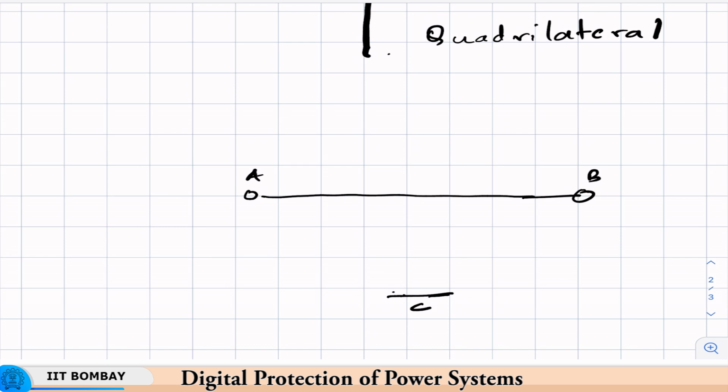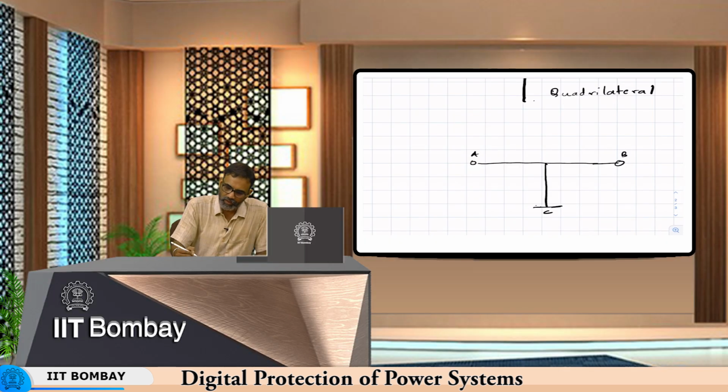So instead of, this is what the diagram shows, this is a tapping. However, realize that if the line is tapped, if there is a fault on any one section, then all, say all A, B, C, all the nodes will lose power. Instead of that, what is done is a loop in, loop out kind of concept is used. So what will be done is, the line is brought into C and then taken out of C again, so that if there is a fault on this section, only AC will go out of service, BC can still remain in service.